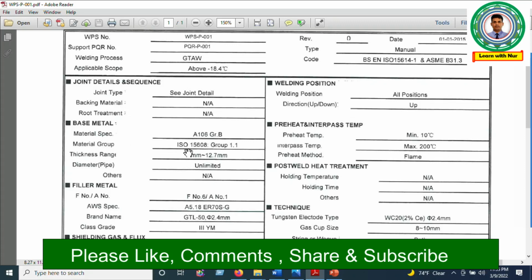Then material group number, ISO 15608 group number 1.1. This is the material group number. What the group number, the P number and the F number are, I will explain in another lecture, one by one. Then thickness range. This WPS is qualified for 3 mm to 12.7 mm thickness.